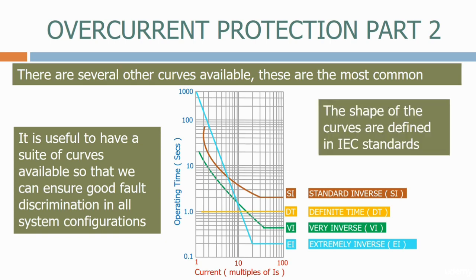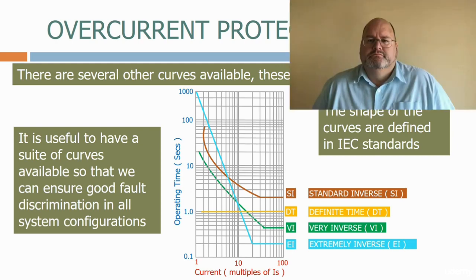The shape of the curves are defined in IEC standards. This is just a sample of the curves available. Modern numerical feeder protection relays contain hundreds of curves and variants, with multiple current detectors which can all operate in parallel.